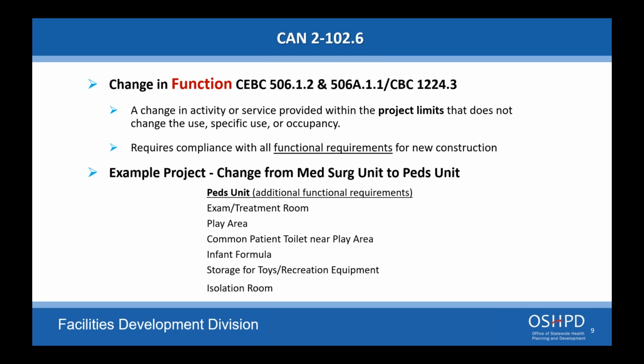Now, turning that around a little bit, and you're saying you're just going to replace a cooling tower that hasn't failed yet but might be getting old, and you're considering replacing it. Again, the scope of the project is replacing that tower. You're still going to have the same seismic requirements and anchorage requirements to do so, and anything affiliated with that upgrade can be done as part of that project. But what it won't do is trigger additional work beyond that.